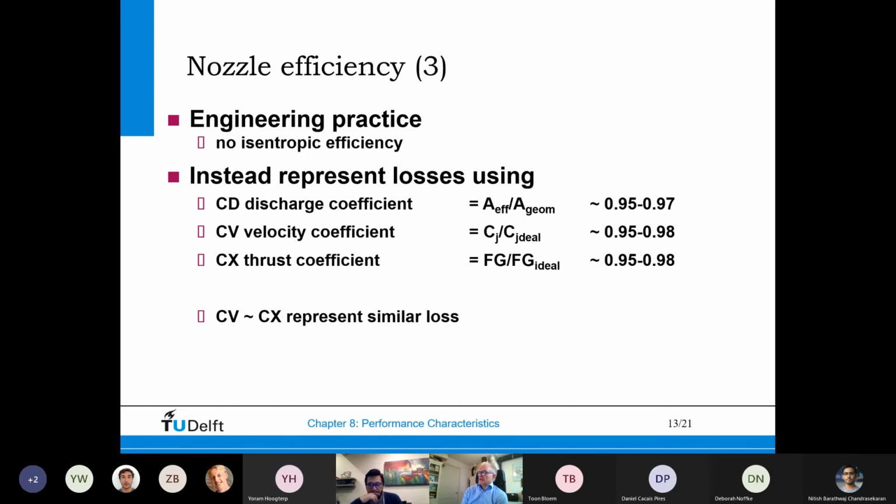efficiencies in the nozzle. Now these values are here constants, but in reality and in detailed models, we establish functions of those factors, typically functions of corrected inlet mass flow.